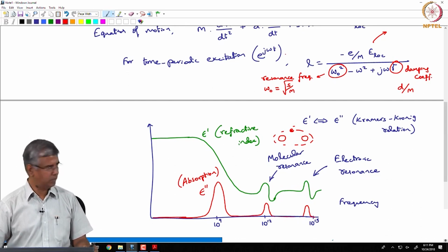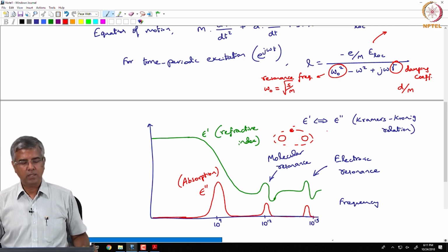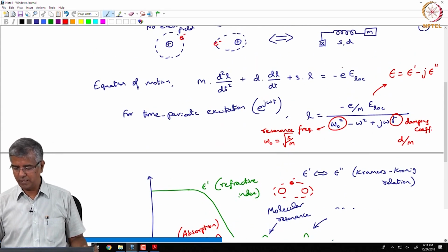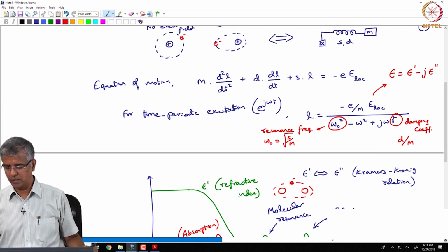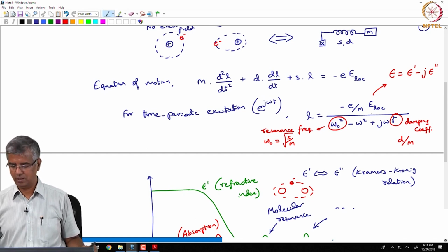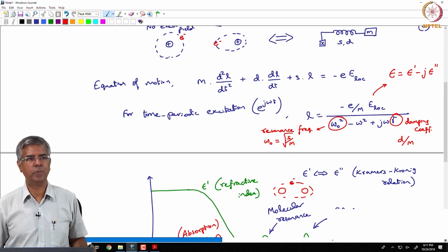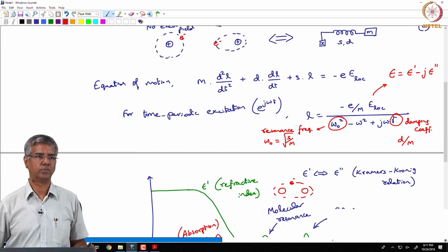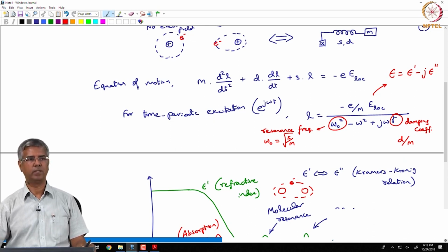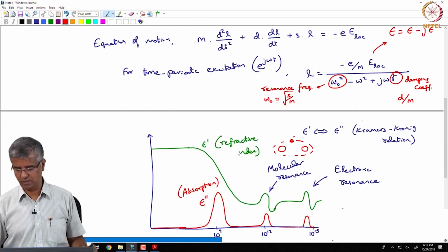10 power 9 actually, sorry. Yeah, 10 power 9, yeah. No, that just comes directly from this. So you can just say even before it approaches omega naught, your response is actually scaling down by omega, right? Higher the value of omega, higher the frequency, your response is already starting to come down. Yeah, it's all coming from that expression there.